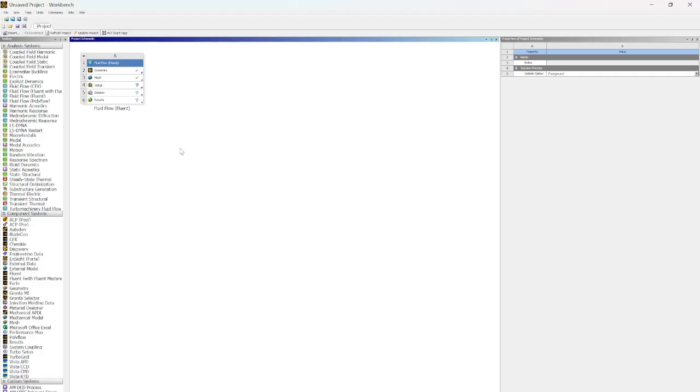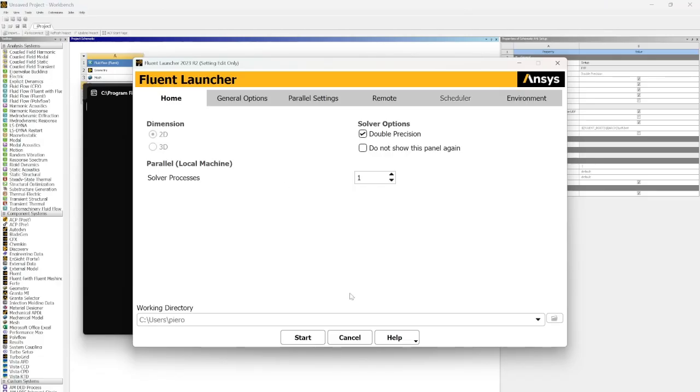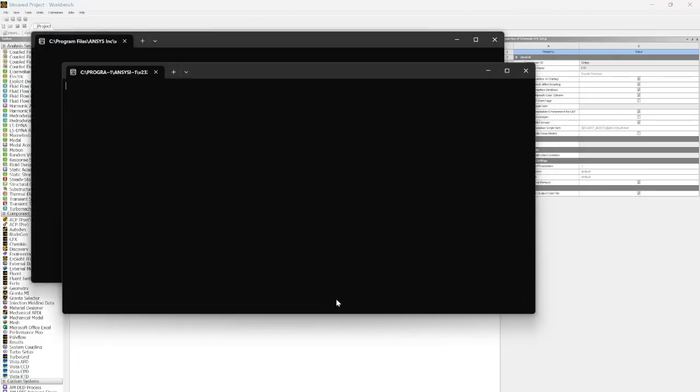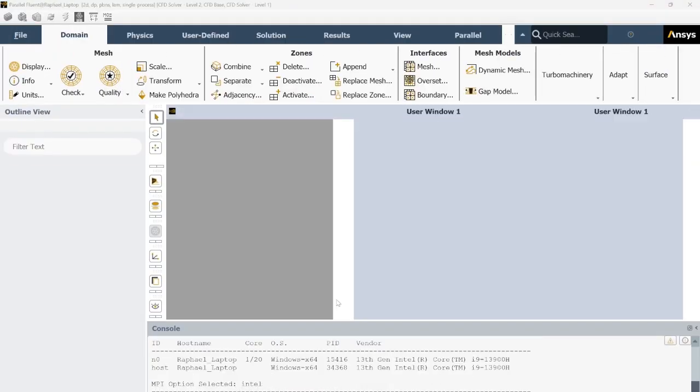So now we're actually going to move on to the Couette flow scenario. I went ahead and changed the length and the height for the pipe in order to maintain the laminar flow that we are looking to achieve. I made the length 250 millimeters instead of 500 and the height 5 millimeters instead of 10. Aside from that, the meshing remained the same.